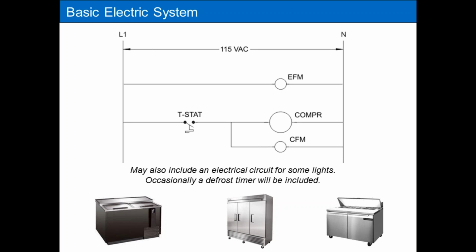So every once in a while you'll come across a condenser fan motor that runs all the time, and the compressor is the only thing that is cycling on and off by this temperature control. And you can verify that by looking at the wiring diagram to see if that's the way the manufacturer intended that system to work, or if a technician prior to you getting there rewired the system so the fan ran all the time. So watch out for that subtle possibility.